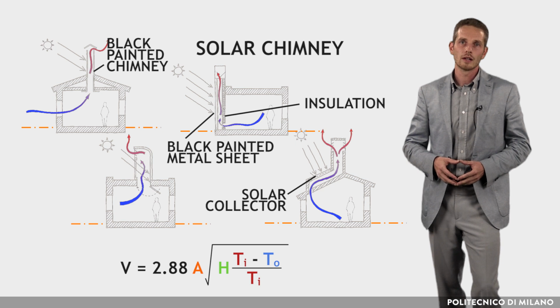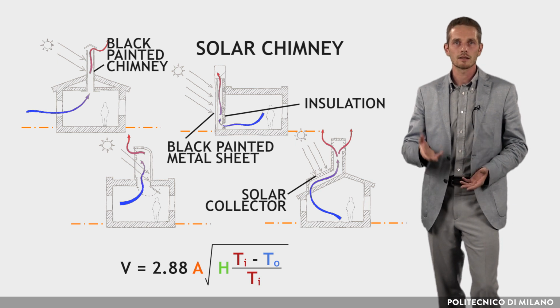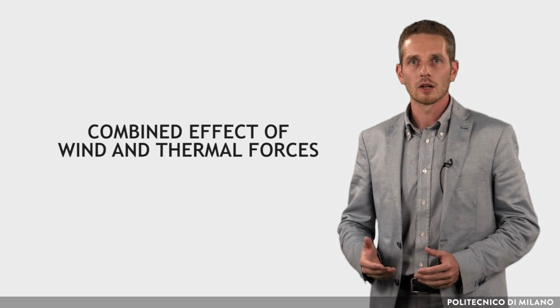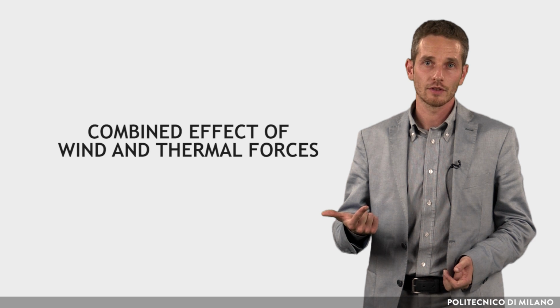To reach this goal, a solar chimney may be provided, exploiting in this way solar energy to heat the rising airflow. The actual airflow in a building results from the combined action of stack effect and wind forces.